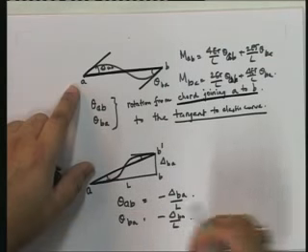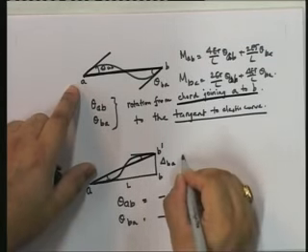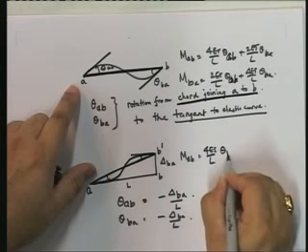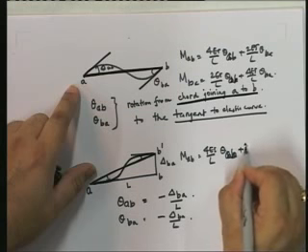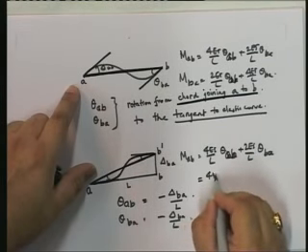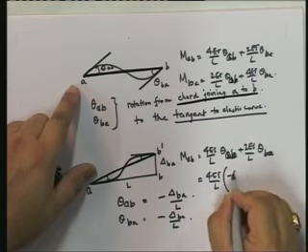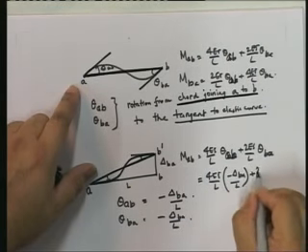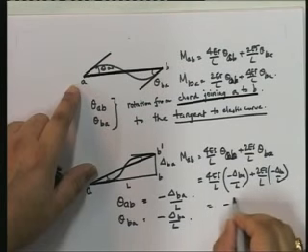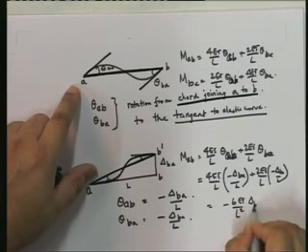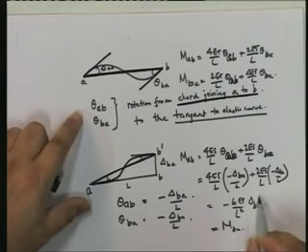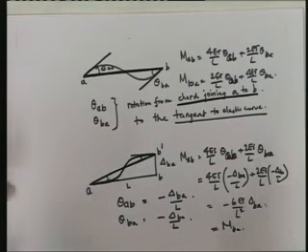Here you see MAB was equal to this thing. So, now MAB is going to be equal to 4 EI by L theta AB plus 2 EI by L theta BA. Now, let me plug this in. 4 EI by L theta AB is minus delta BA by L plus 2 EI by L theta BA, which is also minus delta. Substituting this, you will get minus 6 EI by L squared delta BA, and you will get similar MBA also. The point to note is that we have got exactly the same MAB and MBA as we had got using the earlier definition.